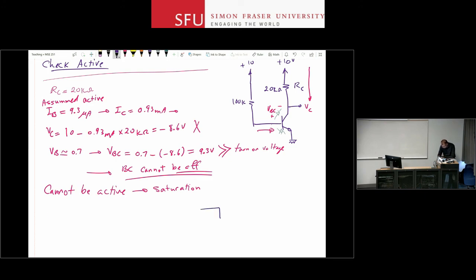So I take the transistor out, put this equivalent circuit for it. So this is 0.2 volts, and let me just write the symbols. On the collector end, I have VCC, RC, and then this is IC.